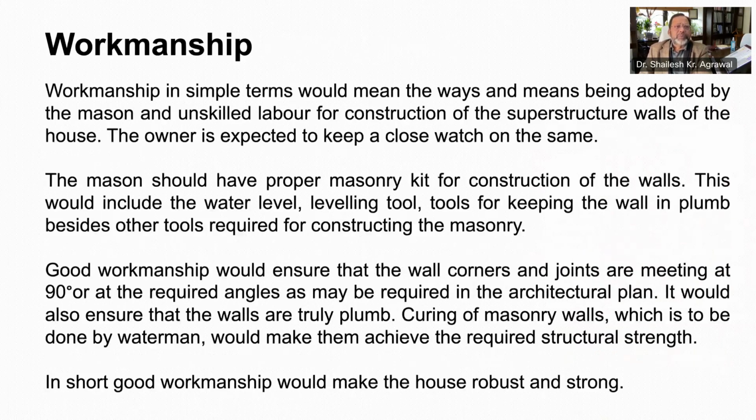Let me also tell you about the workmanship. Workmanship is all about ways and means being adopted by the mason and labor for construction of your superstructure. The workmanship should be excellent, and the owner is expected to keep a strict vigil on the same. Tools like water level, leveling tools, tools for keeping the walls in plumb, besides other tools are a must for the mason to have.